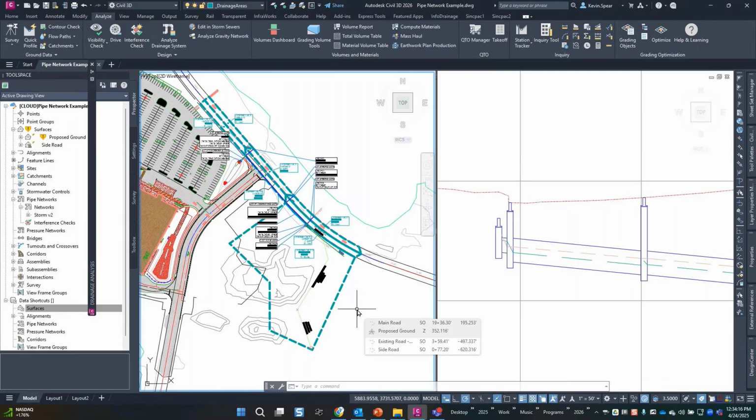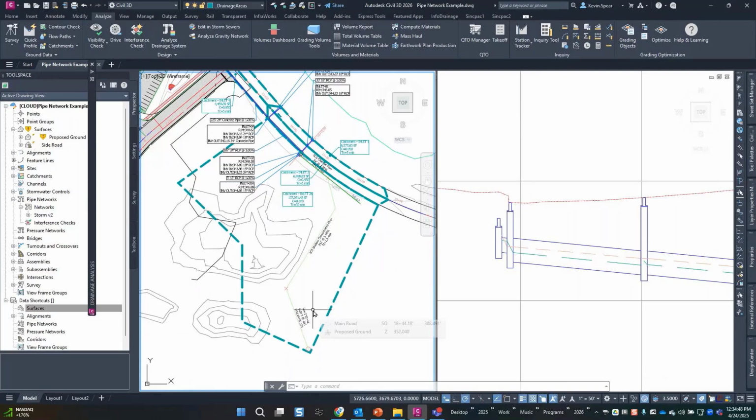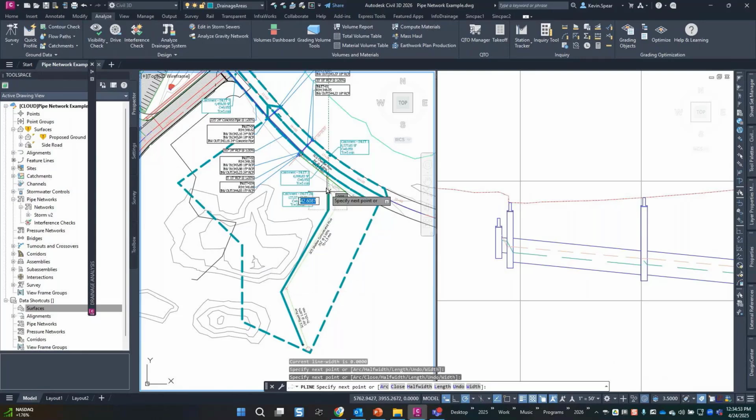What do I mean? If water's going downhill and it sees an adverse slope in Civil 3D, and that slope could just be 0%, a triangle face, it's flat, that time of concentration will stop right there. There's no way around it. It doesn't understand momentum. It doesn't understand any of the normal aspects of what water would do in that situation. It's simply following the slope of the TIN faces. So oftentimes what I do, and that's actually what I did in this case, I simply drew a polyline of where I thought the water was going to go. That's sort of the rough idea, right?